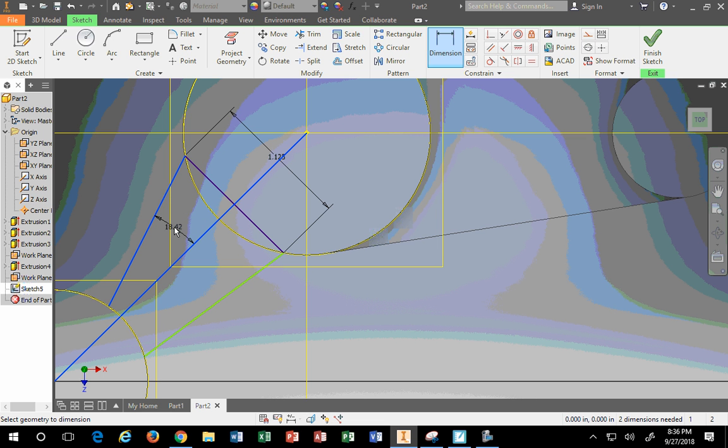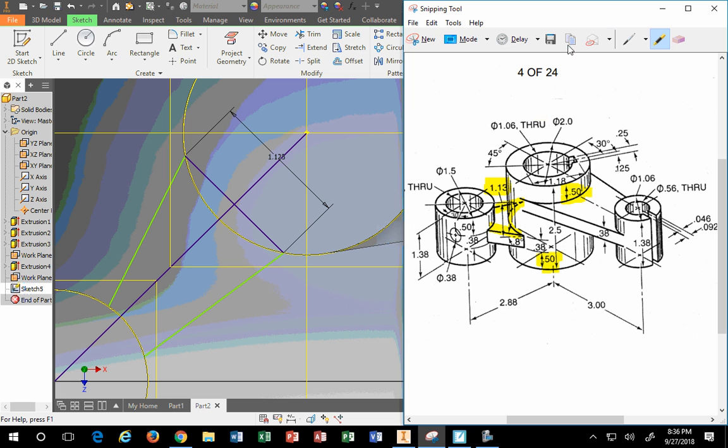But what does the customer give us? Does the customer give us this angle or do they give us the outside angle? The customer's looking at the outside angle. They're looking at this dimension here, from here to here. They're looking at the exterior toe in. They're not looking at the interior flare out. So I can't dimension this from the inside.